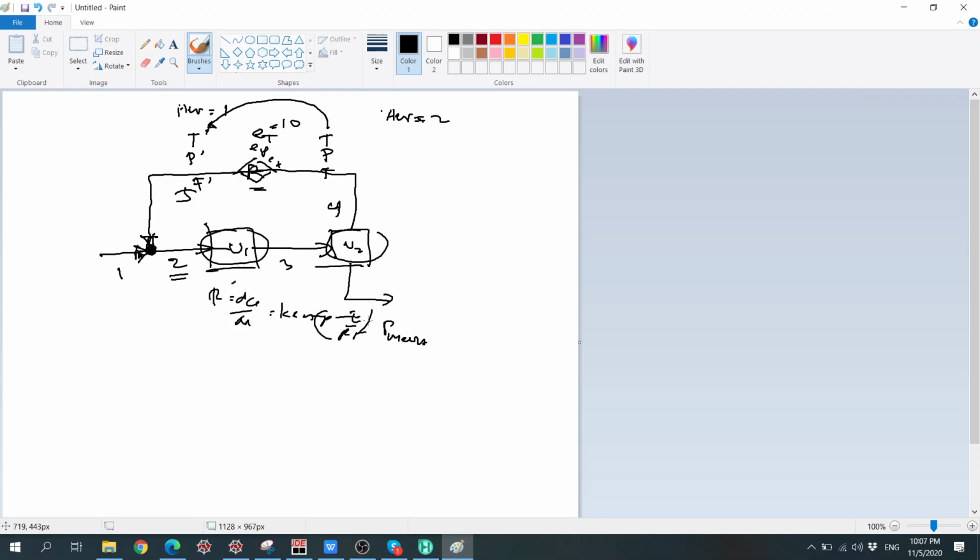And then if you have a different stream number 5, it will make you a different stream number 2. So the partial pressure of methanol will be different as well. Temperature we keep constant because we have a heater there. If this is going to be different, that means this whole thing will be different. Number 3 will be different, number 4 will be different, and if number 4 is different, number 5 has to adjust, and so on and so forth.